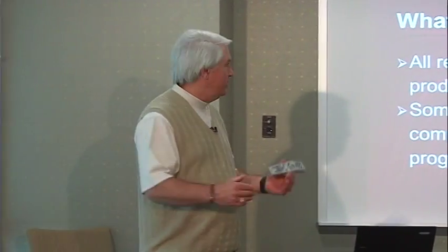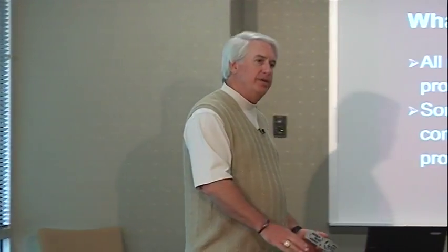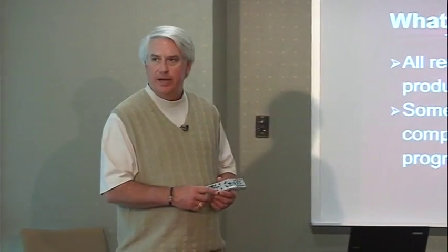When you actually look for a volume, it says all of these require a minimum amount of product inside the tank to conduct a valid test. So we had people that showed they'd passed their monthly release detection at 0.2 when actually they didn't have enough product in their tank, so it wasn't a valid test.